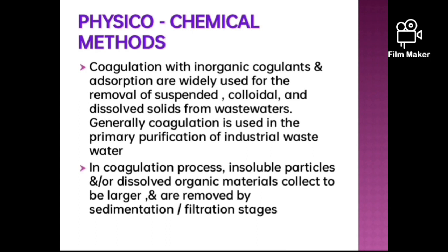Generally, coagulation is used in the primary purification of industrial wastewater. Second, in coagulation process, insoluble particles and dissolved organic materials collect to become larger and are removed by sedimentation or filtration stages.